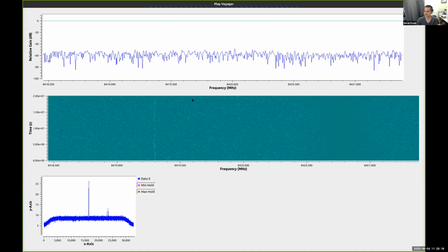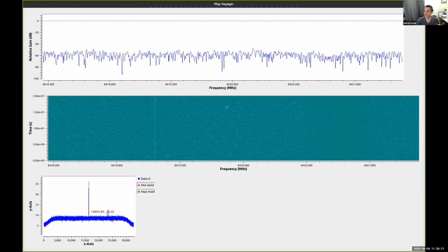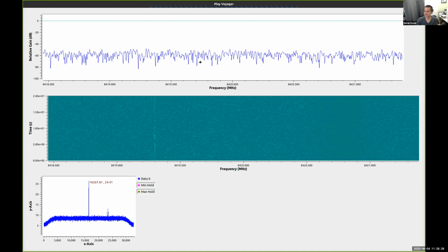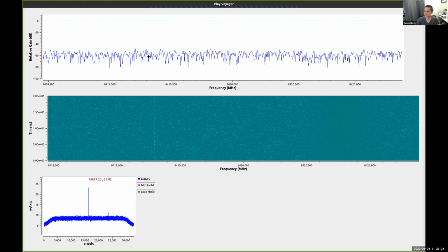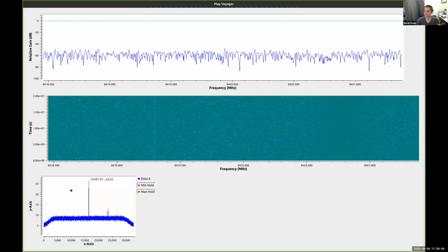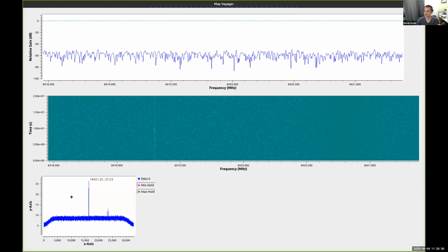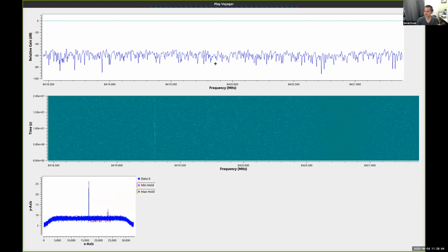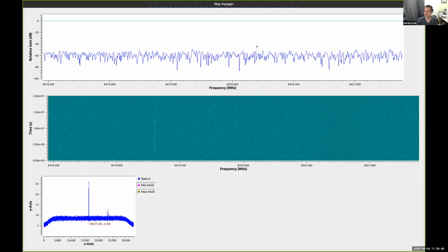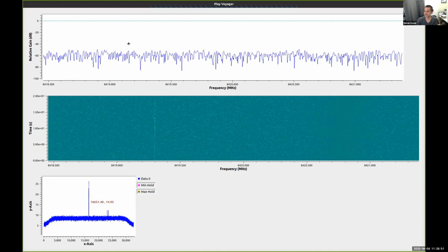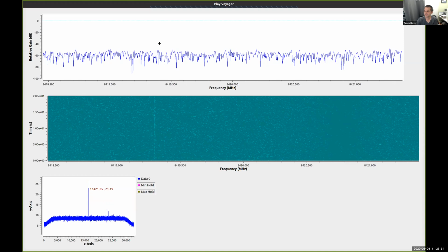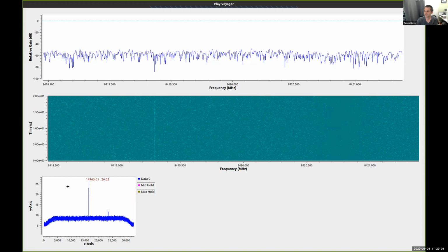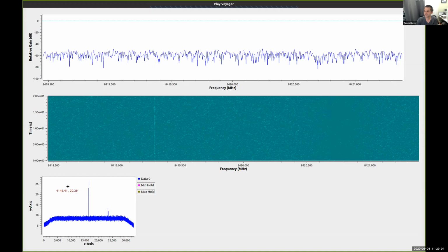So compared to doing a long averaging here, if I increase the FFT size a bit, we'll see a closer comparison. We are getting a cleaner image here because we're doing a much finer Fourier transform and a much longer integration than the display here is doing. I can't really fool myself into thinking that we can see the spurs off on the side of the averaged one. So that is how to do a spectral integration within GNU Radio.